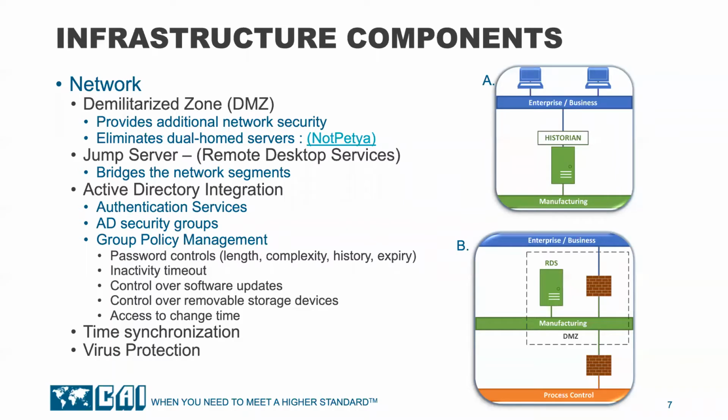Just a quick note about isolated networks. I've heard clients comment that they were safe because they had an isolated network and therefore didn't need virus protection. Virus protection is imperative because almost no network is truly isolated. A vendor may put their laptop on the network or put a thumb drive in a workstation, and more often than not, there are connections between networks for printing or internet access that people have not taken into consideration.